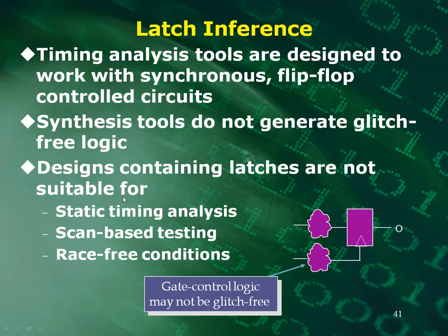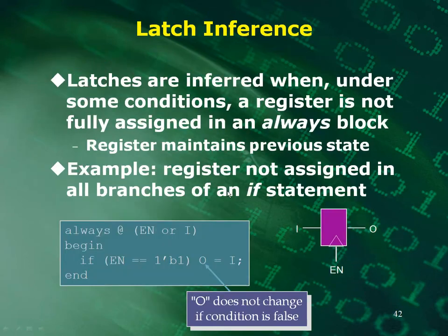Okay, designs containing latches are not suitable for static timing analysis. When I say latches, I'm not talking about flip-flops, I'm talking about latches. And they're not suitable for scan-based testing and race-free conditions. So stick to combinational logic and flip-flops. Latches, you're going to need to know what you're doing there. They're just problems.